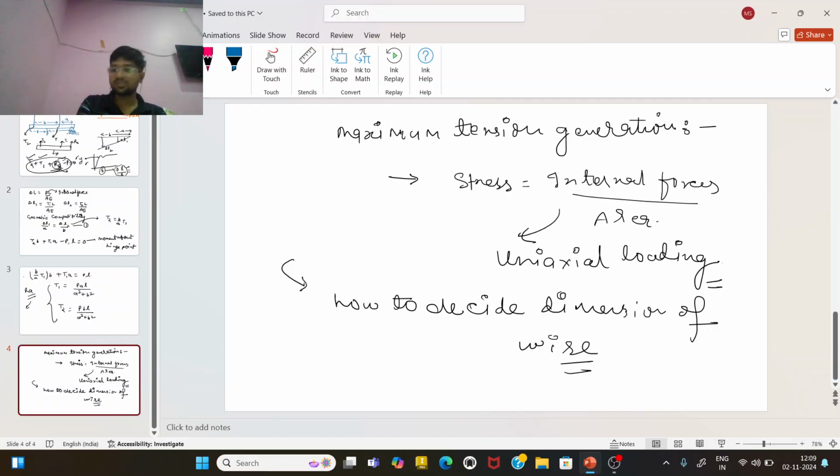This is not a new thing, it's basic common understanding. The basic approach to solve this type of problem is: when you see the problem, first write the moment equations and force balance, and then write the geometrical compatibility equations. This is a simple process to solve an indeterminate type of problem.